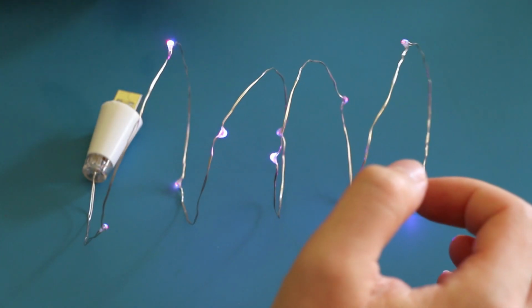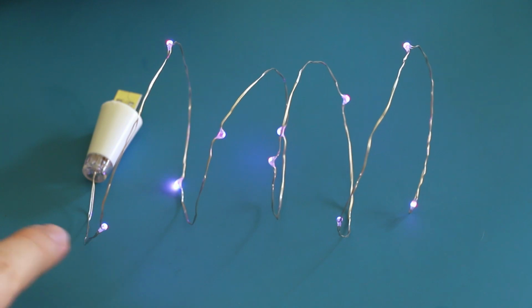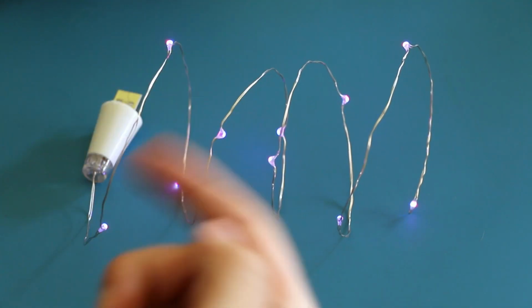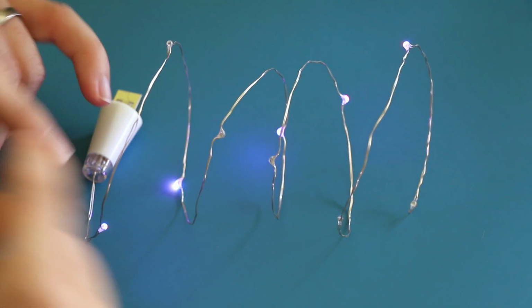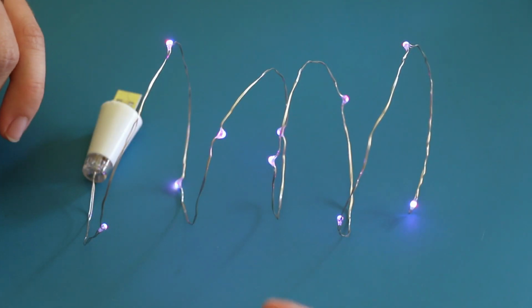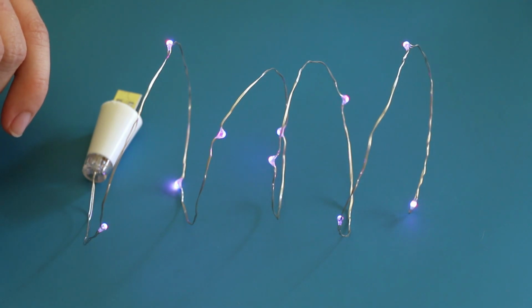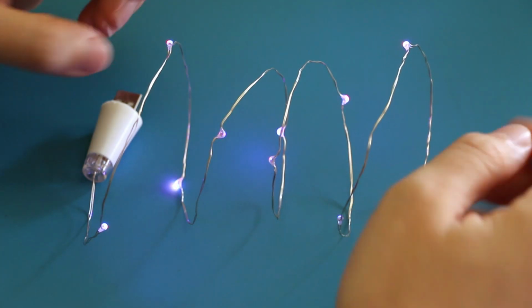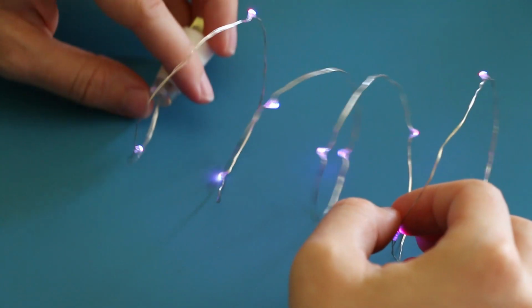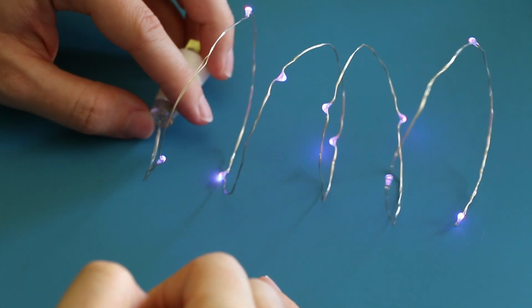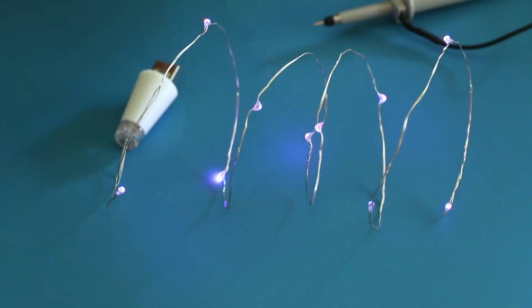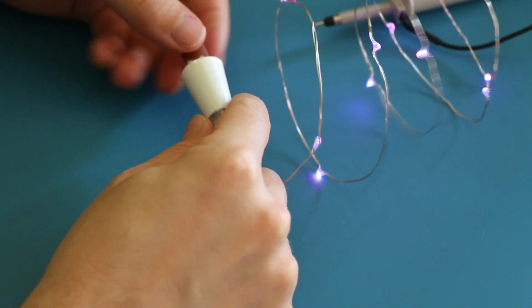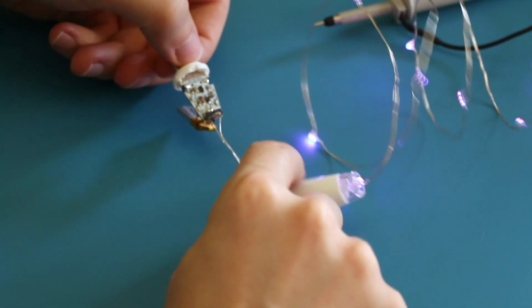Now, as established previously, these LEDs have a red, green, blue control as well as an address system, which allows us to identify two independent chains of all of the odd LEDs and then all of the even LEDs, and individually control their colour and brightness. If we hook this back up to the scope, then we can have a bit more of a look into what's actually going on and try and understand how the PWM is being implemented. So if we remove the cap again, and then hook up to that wire that we were using previously.